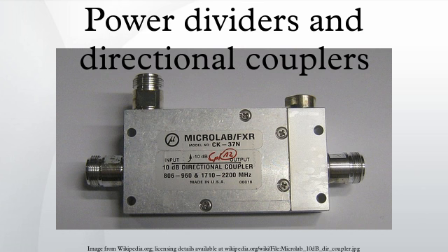Power dividers. The earliest transmission line power dividers were simple T-junctions. These suffer from very poor isolation between the output ports. A large part of the power reflected back from port 2 finds its way into port 3. It can be shown that it is not theoretically possible to simultaneously match all 3 ports of a passive, lossless 3-port, and poor isolation is unavoidable.